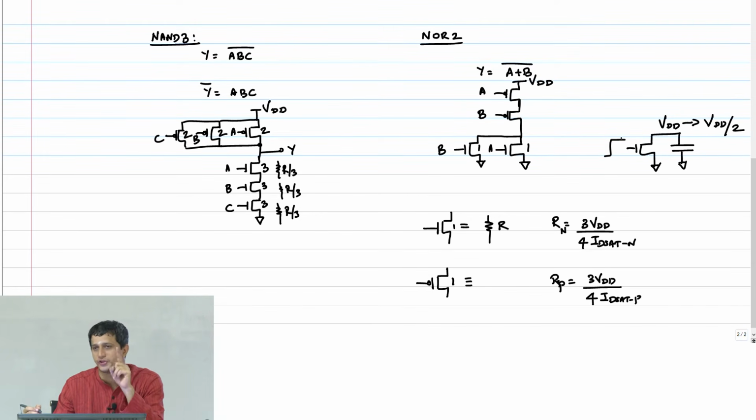It is discharged initially and it has to charge to VDD by 2, right. So an identical scenario will occur there because the VDS of the PMOS will start from VDD and go exactly down to VDD by 2, right. So you can evaluate that, just to tell you. So this would give me an equivalent resistance of R, that's what I am saying.